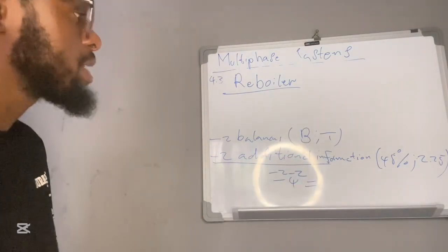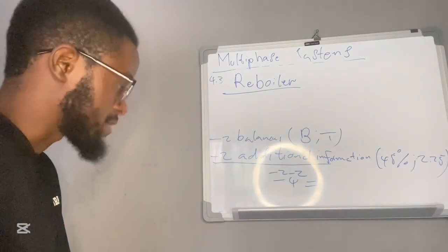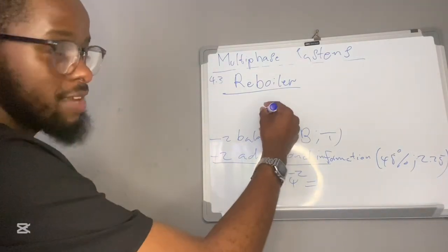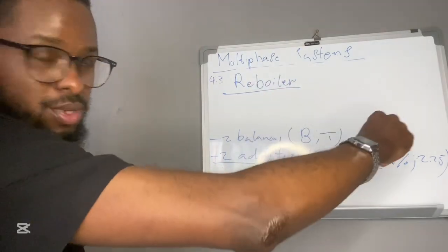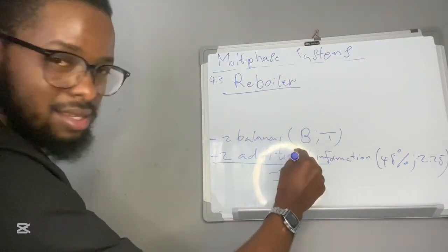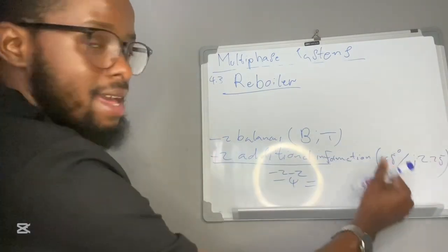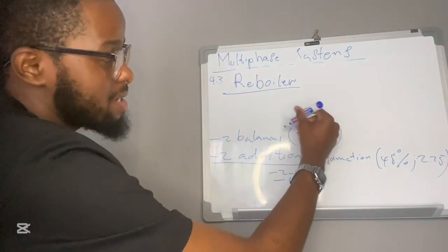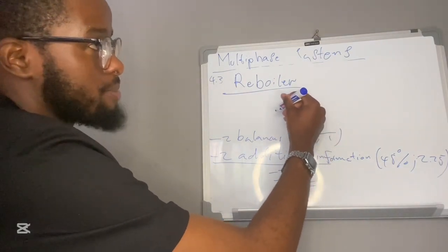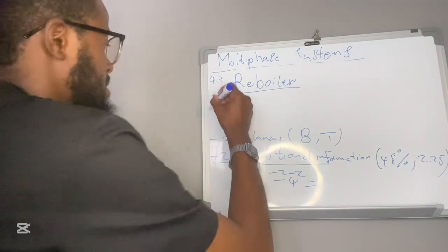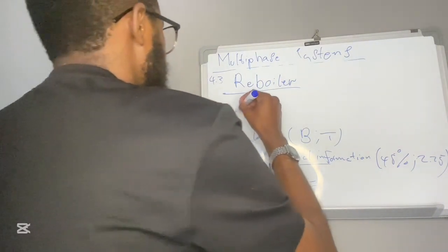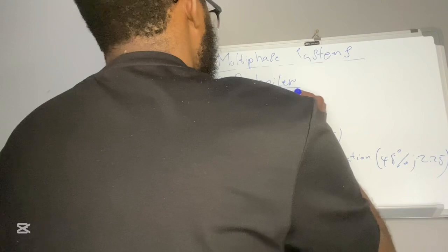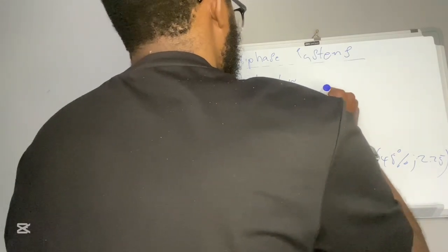Okay. So how many unknowns do we have in the reboiler? We have 6 unknowns in the reboiler. We have N2 as liquid, ZB, N3, XB, that's 4. We have N4, that's 5, and vapor YB, 6. We have 6 unknown variables.